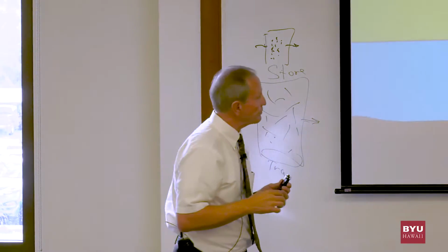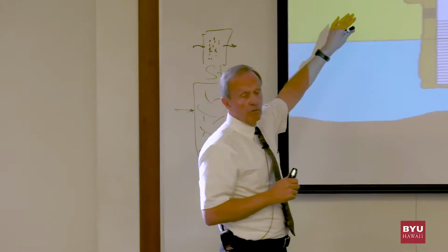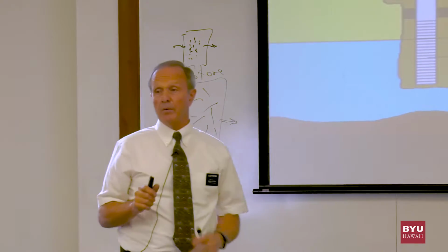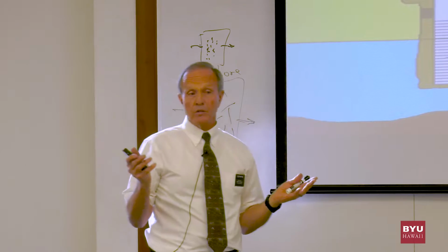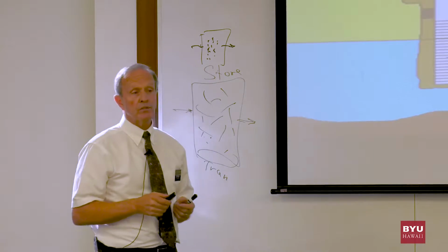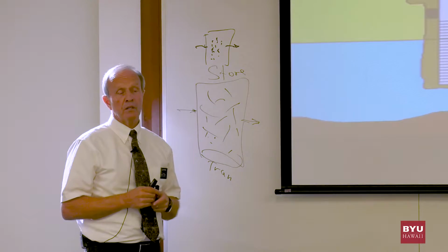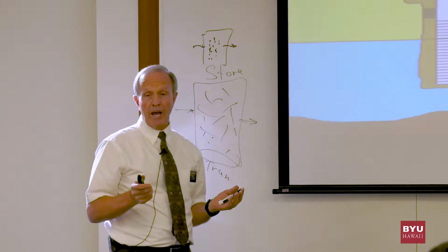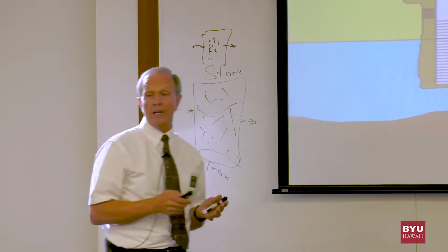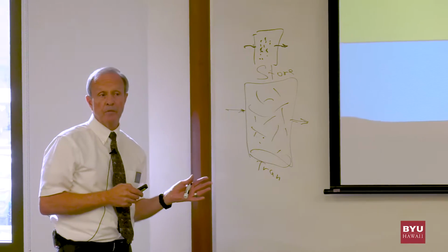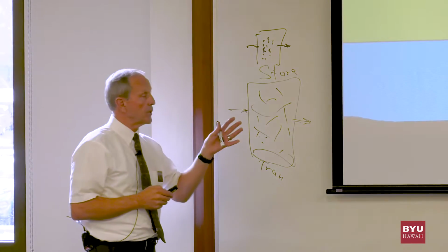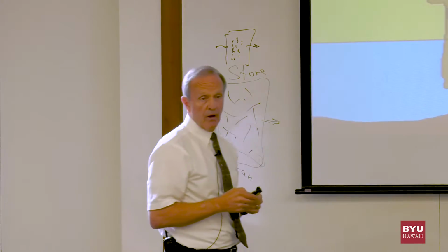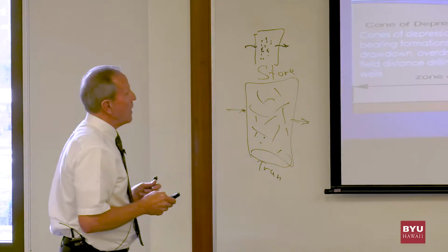So what we had to do is go to stainless steel. When you put stainless steel in a 16-inch and it's 1,200 feet deep, you don't have to go that deep, you're going to be up to $350,000 just in your casing. But the deal is the casing will last. With your carbon steel, you have to throw that out every 2.5 years and put new carbon in. So it was a lot more practical to put in stainless and let it run for 30 years versus jerking it out. You didn't have a choice.